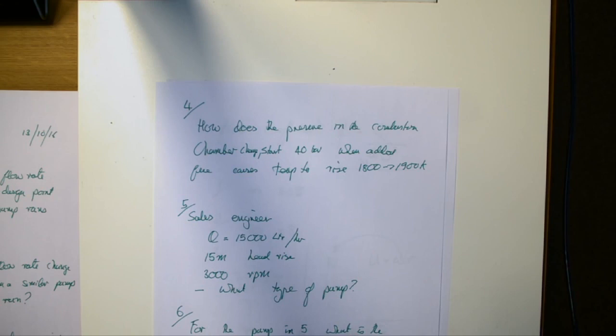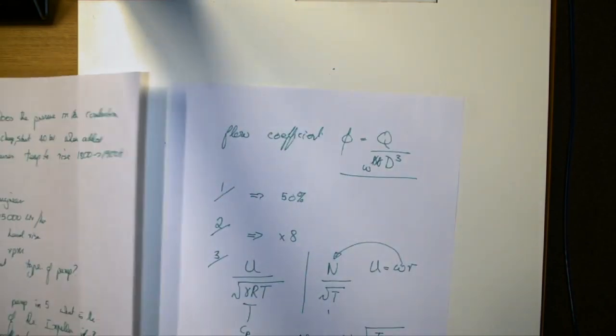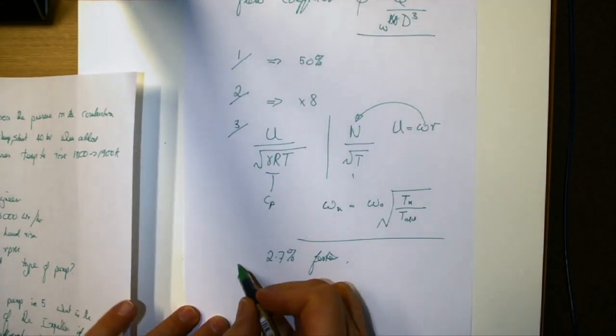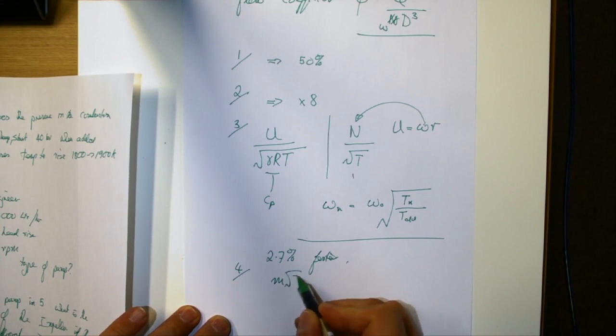It's not far off. But this is a dimensional analysis lecture. Yeah. I guess it's using the formula you have on 417, which is the mass times the square root of CP T1 over D squared. Hooray. Good man. That's what's required. So question 4, the value m root T naught over P naught, I'm calling them naught here because they're stagnation quantities, but it doesn't make a lot of difference because the velocities in the combustion chamber are negligible.